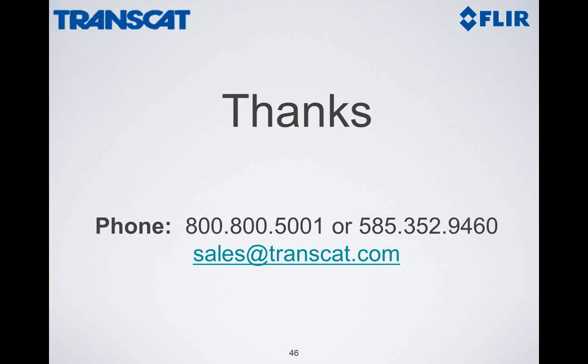So really, it depends on the size of the target that you wish to measure. And ultimately, you would like to have a minimum of 3 pixels across your target. You would like to have 3 by 3 pixels, so you would have 9 pixels on your target size. And the fine people at Transcat and FLIR can help you select the right camera.